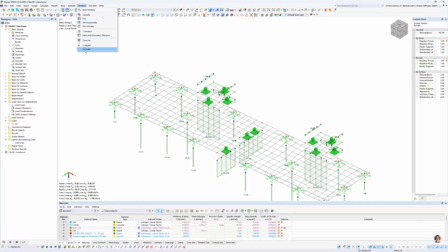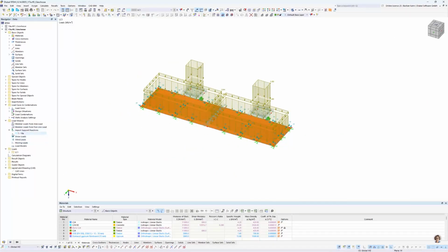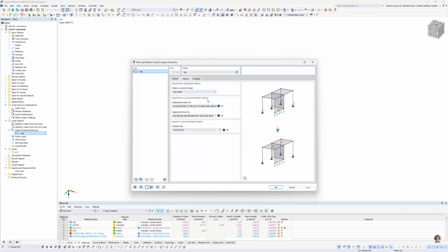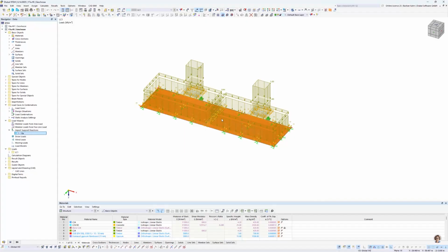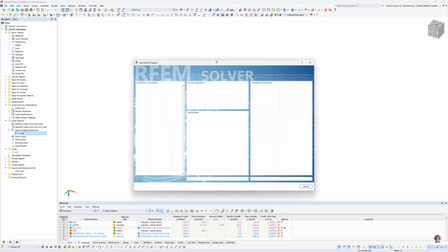So all this stuff is in there. And then go to the story underneath it and say, okay, the connected model is 18. So the 18th story. What supported nodes do I have in the other model? What loading am I getting there? And now when we switch off this and calculate it, it's keeping the information or the support forces from the other model, was it 28.9 kilonewton?